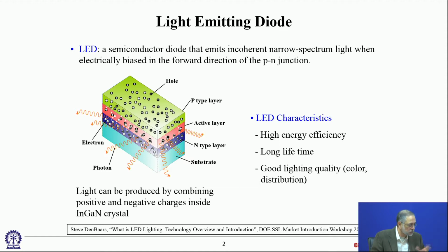So some particular kinds of semiconductors are better at giving off the energy as photons rather than phonons. Those are the ones that we use as LED devices. A particular kind of doping, a particular kind of semiconductor material, favors photon emission rather than phonon emission. That's basically all it is. It's a semiconductor diode, a p-n junction, that typically emits a narrow spectrum of light.